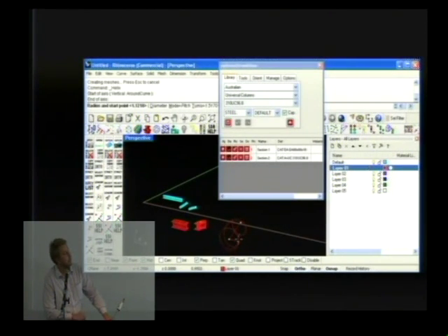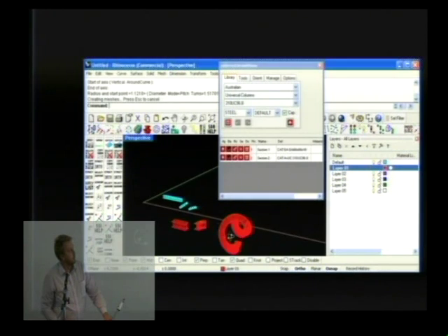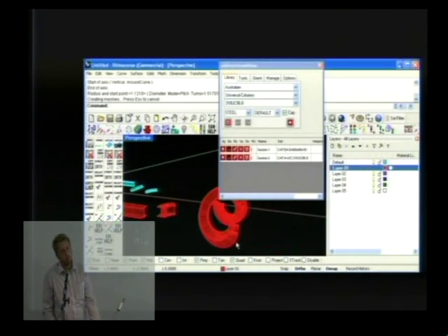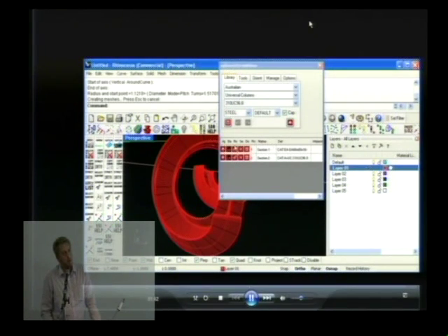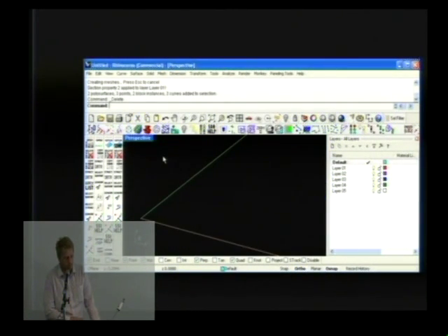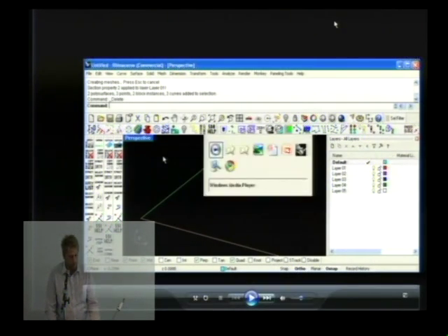One of the main reasons why you might model in Rhino is that it's fantastic with curves, with the NURB surfaces and curves. In Rhino, it doesn't care whether it's a straight line or an arc or a helix of some description. It will sweep that profile over that curve. So you have a lot more freedom in the shape and form that you can explore in a program like Rhino. Whether it can be cheaply built or fabricated might be another matter.